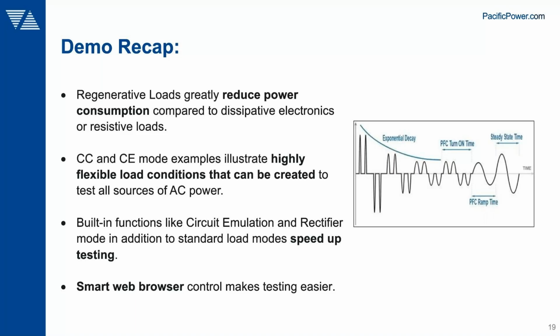And you can tweak that as well to make it meet your requirements. Or you can create an arbitrary waveform and do the same thing there by switching waveforms as part of your load settings. So those are very powerful capabilities and make it very easy to come up with very complex load scenarios to really shake out and test your designs as far as your power source designs.